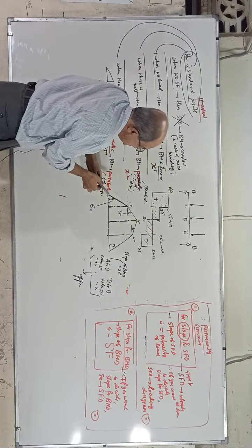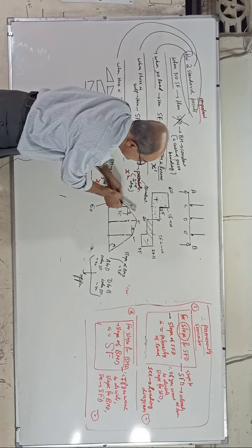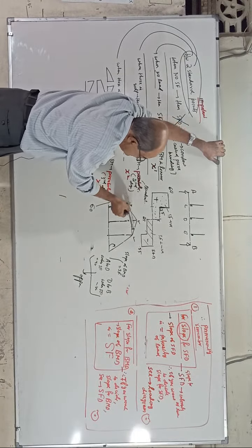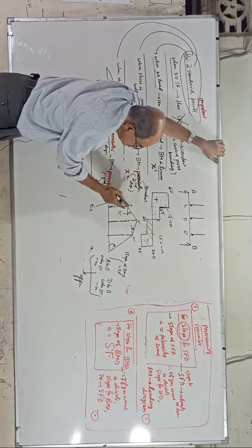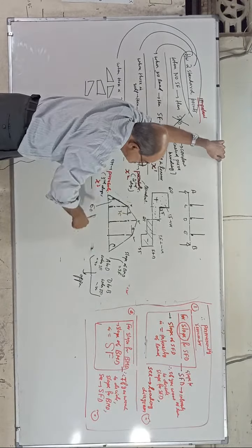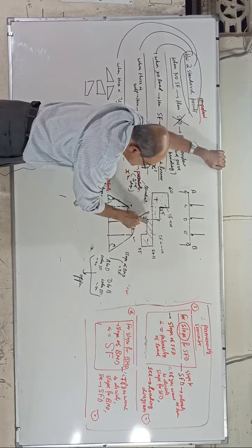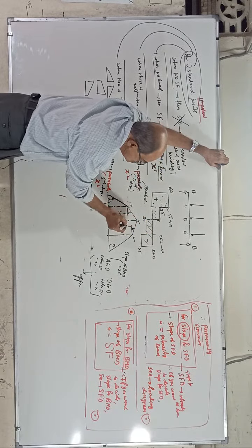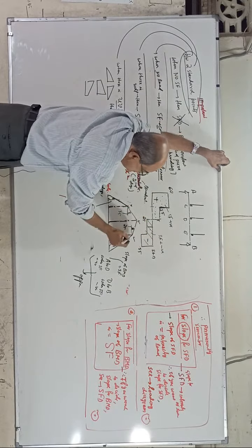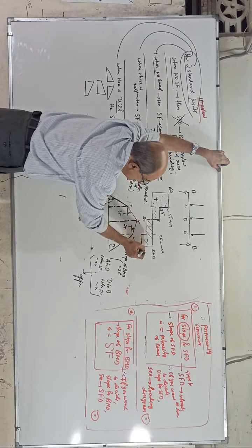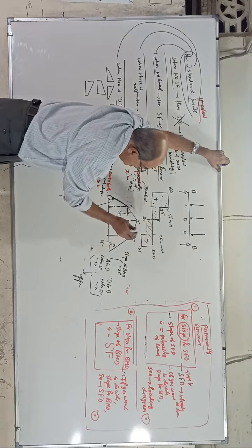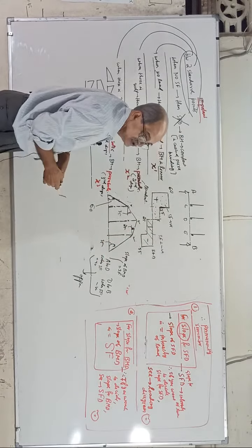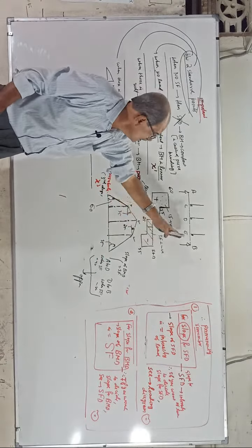Correct? See here, this is steep. That is a little flat. See, this is steep. Why? 60. That is flat. Compared to this one, the slope should reduce. Then, when you come to this side, for this line, slope is 25. Whereas for this line, shear force here is 55. Slope should be 55. Again here, this should be steep. This should be flat. Correct? This is the explanation for point load.